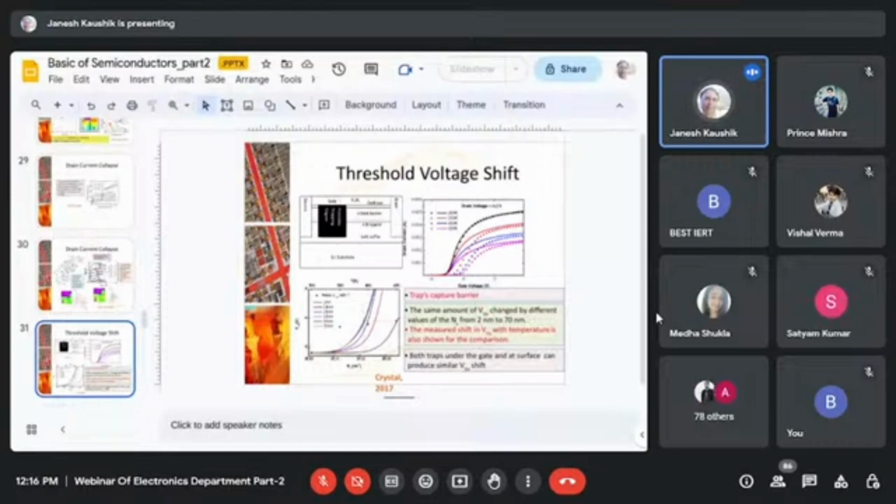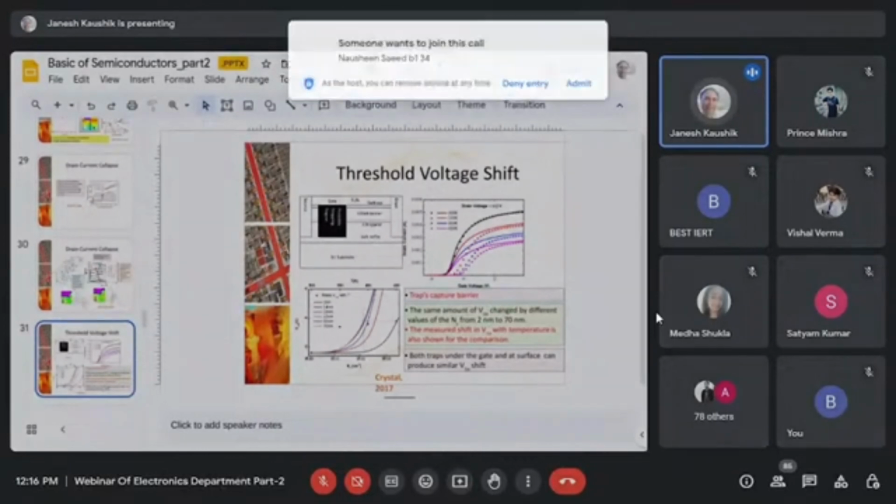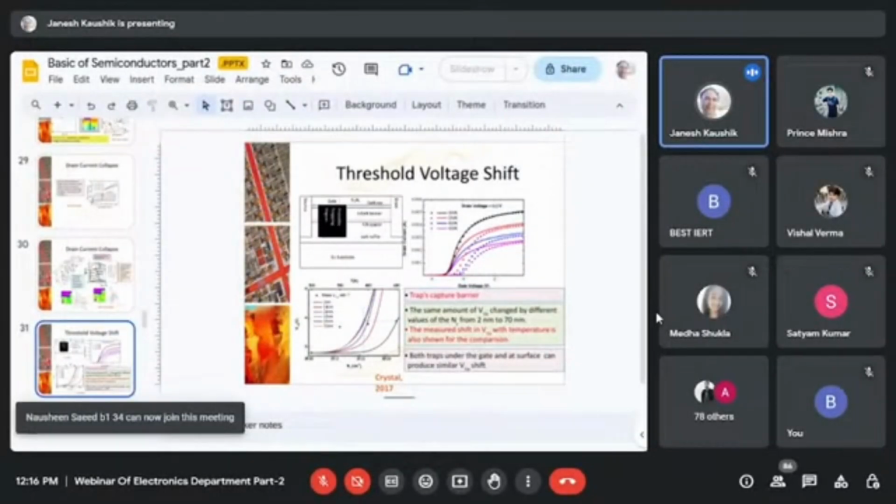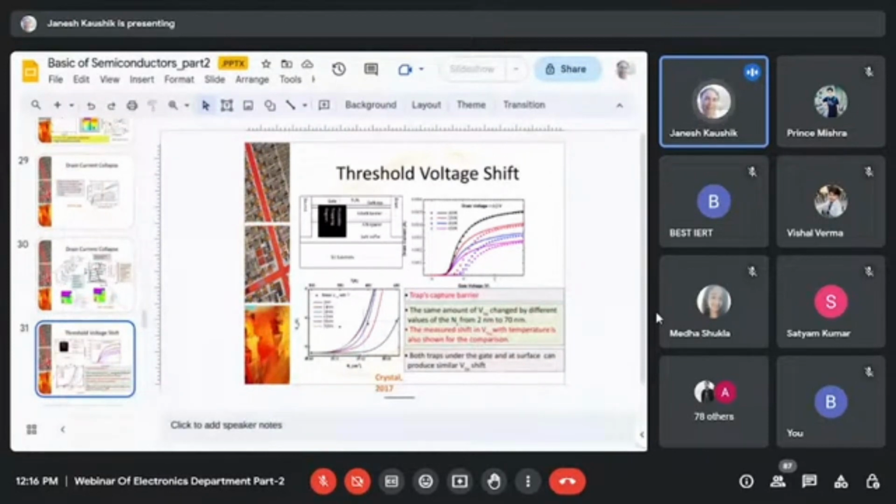And then, by the simulation and by the capacitance-voltage measurement also, we can calculate where the physical location is. The one challenge in the measurement is that because the AlGaN layer is not doped, it is completely depleted, and when we apply a gate voltage, the 2DEG is completely depleted within less than 1 volt or 500 millivolts.